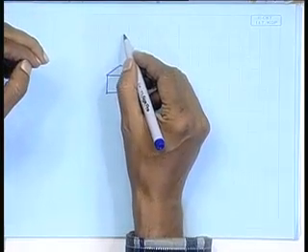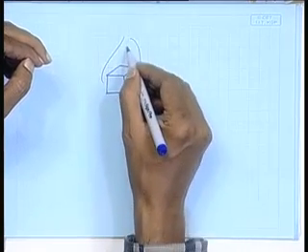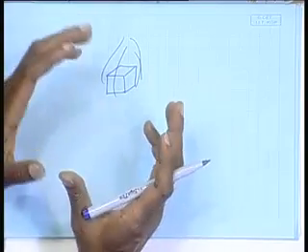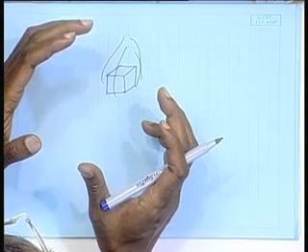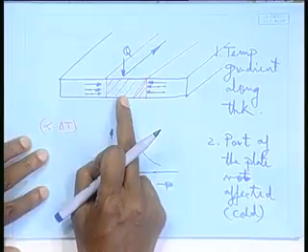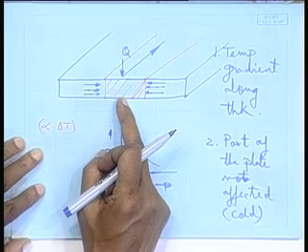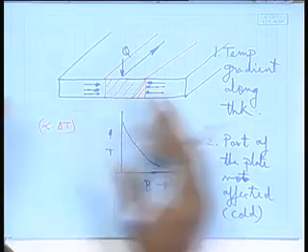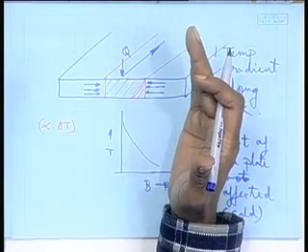There I used a kind of heating such that it is uniformly heated all around. So, transverse shrinkage will take place. That is what I said in the first case, that if there is no temperature gradient across the thickness, then only transverse shrinkage will take place.